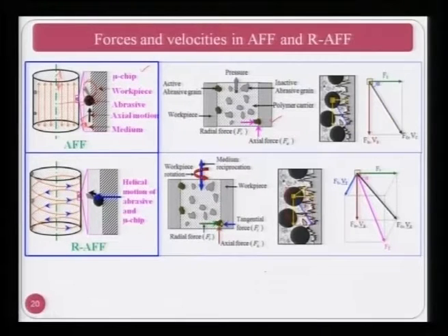Now, how it is shearing the peaks is shown in the last figure, and you can see smaller pieces that are removed in the form of microchips by the abrasive particles. The last figure on the right hand side shows the radial force that is acting on the abrasive particle and the axial force that is acting on the same abrasive particle, and here is the cutting force or resultant force Fc.